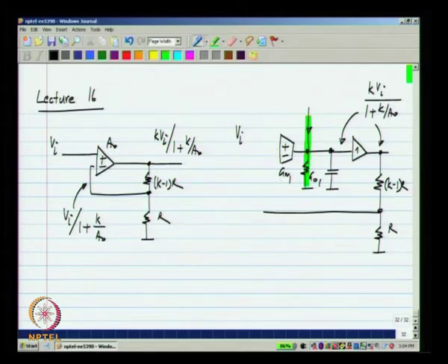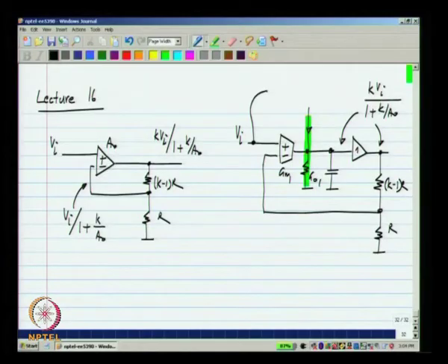And that is exactly what the original negative feedback idea was doing, that is, you want to control some quantity based on the error between some desired quantity and some controllable quantity. So how did we do that? We took the difference between the desired and actual values, and we integrated that over time, and in this case the integrated quantity, the output, should be a current which is related to the integral of this difference.